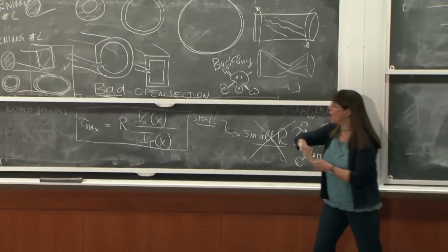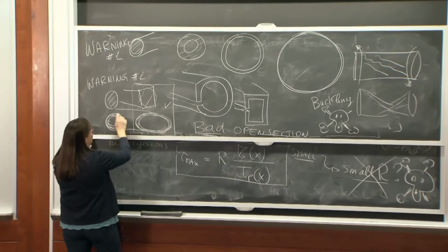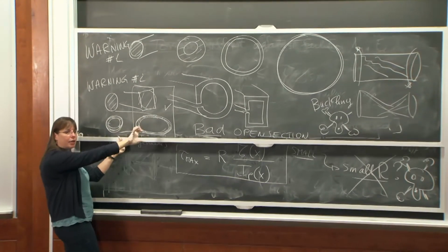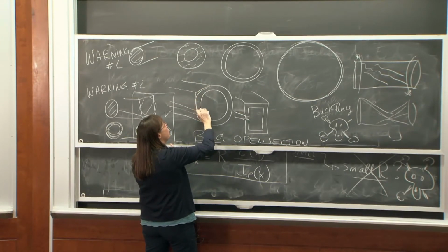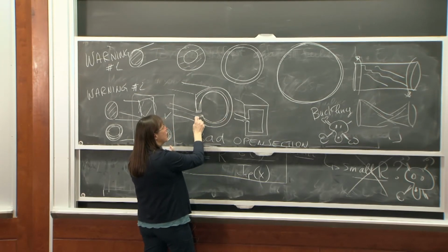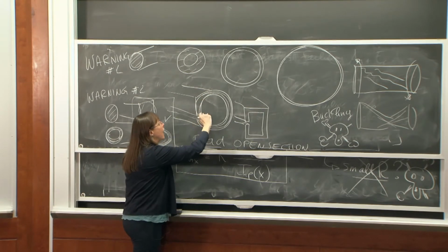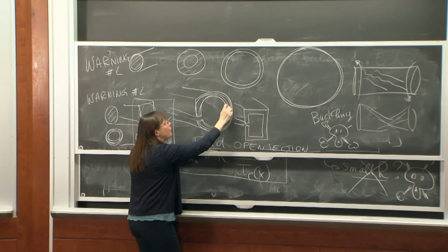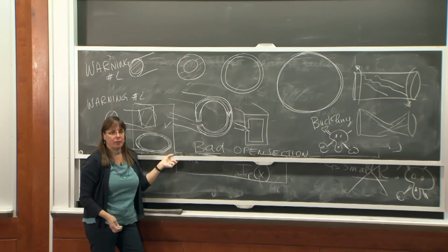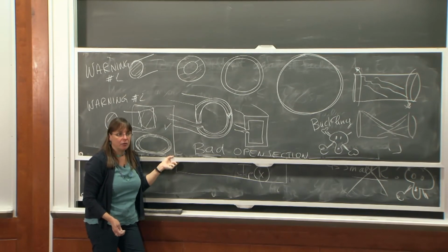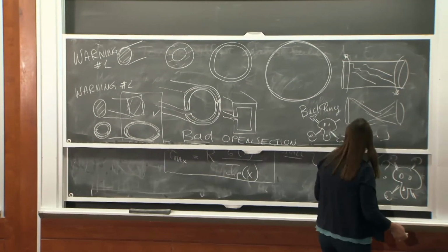In torsion here, the flow of the river is all around, and the flow of the stress all around gives you the resultant torque. Here, your stress has to go around here, come back here, do this, and come back like that. That's how it carries torsion. Like this, down and up and down and up. Lines go this way here, that way there. What a mess. It's like a traffic jam. Very ineffective. So if you design things in torsion, not open cross-section.